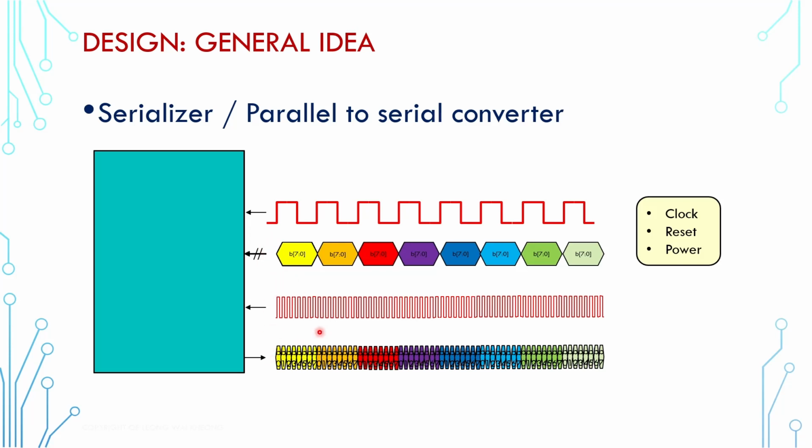1. Where is the source of the fast clock? There is an upstream component providing the input data. It's reasonable for it to supply this input clock. However, it's not responsible for this output data, and therefore it doesn't make sense for this fast clock to come from the upstream component. Another problem is that if the fast clock comes from the upstream component, this design is pretty much helpless when the fast clock is not synchronized to the slow clock.